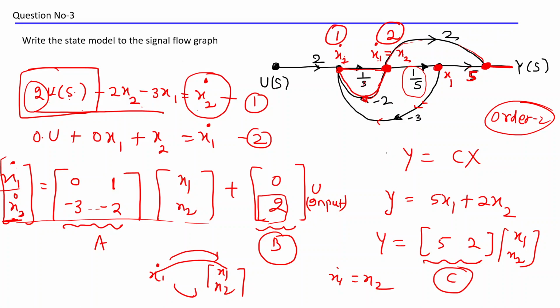One by s are the integrators in Laplace domain. Then there are two, order is 2. Then I have to choose one integrator first. Let's see, I am choosing this integrator first. Okay, 1 2 3. I am choosing this node 3 as my x1. Then if you are going back, means forward path is an integrator, backward path is a differentiator. It means this one x1, then this node 2 should be your x1 dot. It's a differentiation. I am assuming that x1 dot equal to x2.